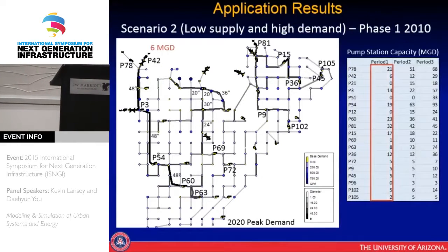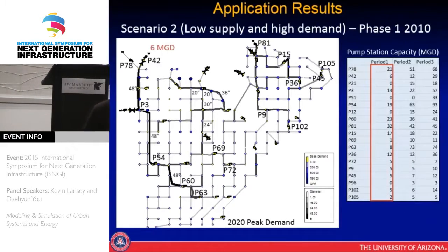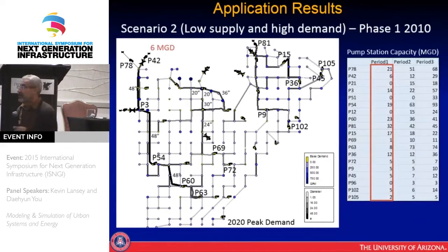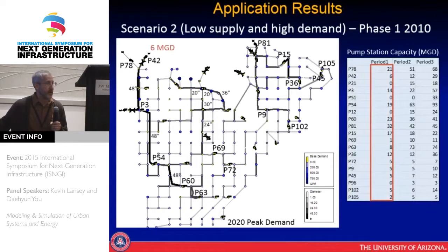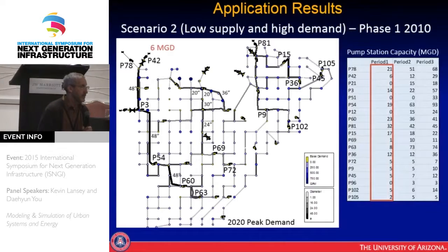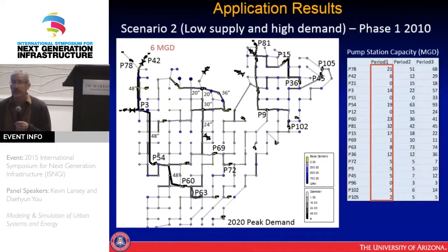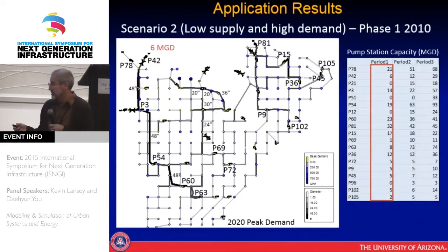There's our problem. It's a relatively complicated problem in this case because we have a highly nonlinear system. Describing water flow is a nonlinear system, so it becomes a difficult problem. We have lots of decisions, and we're solving this with a genetic algorithm because of the combination of those two things. It takes us about a day to solve one scenario on an 8-processor parallelized solution. So it's not an easy problem for us to solve, and you'll see why that impacts us on the acute disturbances in a little bit.